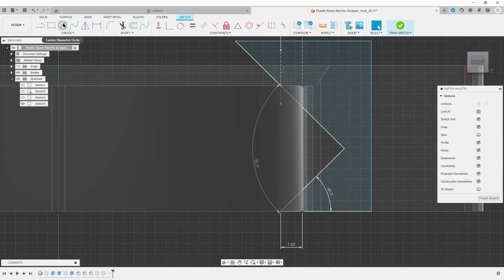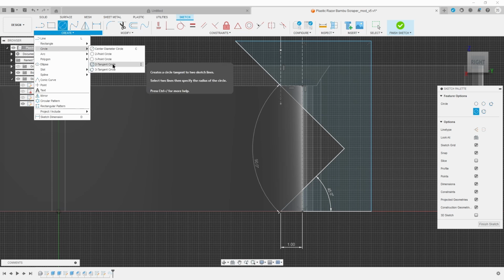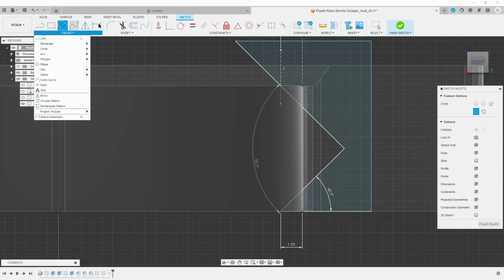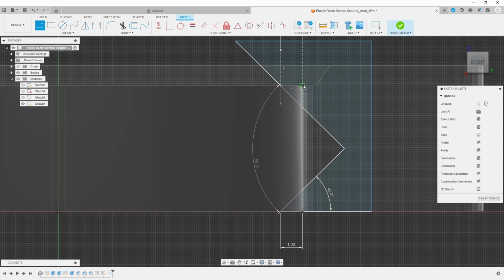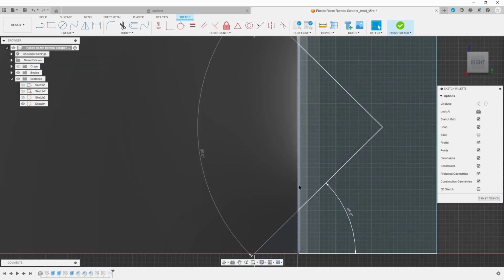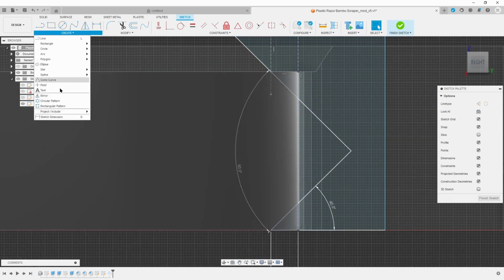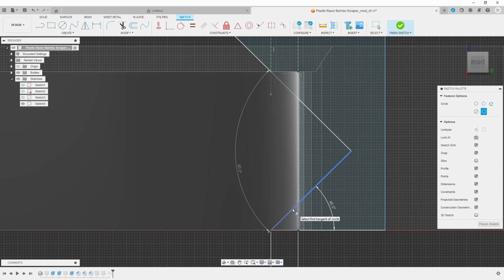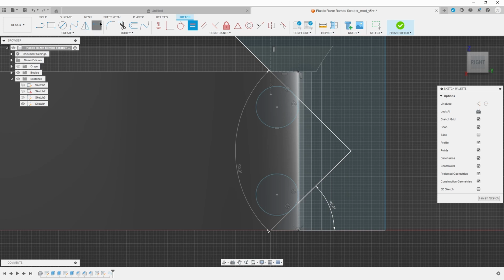Now, going back into the sweep tool, you can do much more complicated things than a simple chamfer. What I like to do is to have a chamfer on the bottom and top just so it's symmetrical. But when it's printing, you need the chamfer because you can't put a radius towards the build plate, because the changing angle creates an overhang that's a problem where it's touching the build plate. However, on the other end of the angle, you can actually put in a radius and you won't have any issues with it. So right here, it has to be straight. It has to be a chamfer. But up here, you can blend into a radius.